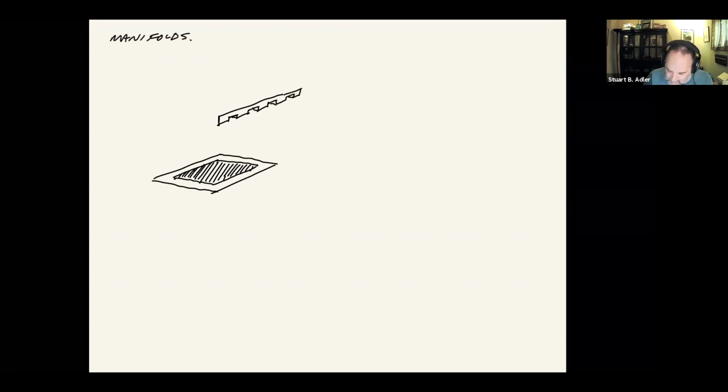What I'm going to try to do is design it in a way that this surface right here and this surface right here are going to form seals all along one edge of this plate like that. And then the other one is going to form a seal like that. So the gas is going to approach from one side. Basically, air is going to come in this way, and because of those seals, it can't squeak out the sides.